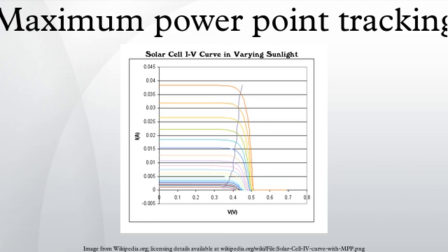The maximum power point voltage can then be computed from the characteristic curve at the same intervals. Constant voltage. The term constant voltage in MPP tracking is used to describe different techniques by different authors, one in which the output voltage is regulated to a constant value under all conditions and one in which the output voltage is regulated based on a constant ratio to the measured open circuit voltage.